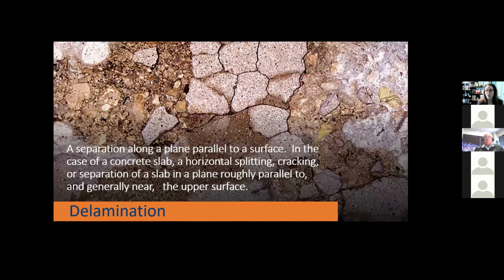Blisters sometimes come with other issues of trapped bleed water. Another example would be delaminations. Delaminations are when you have a fissure or a separation, basically a crack, right underneath the surface of your concrete. So under that top 1/4 inch or 1/8 inch, you now have a separation of that surface layer, just like I was talking about for repairing dusting.